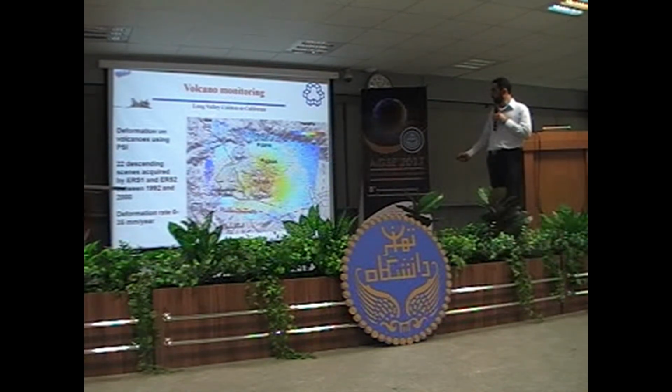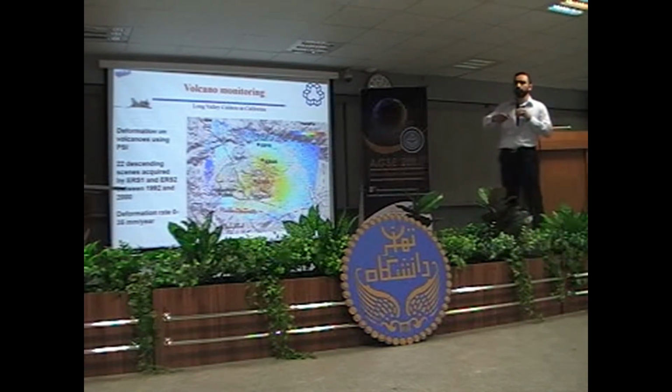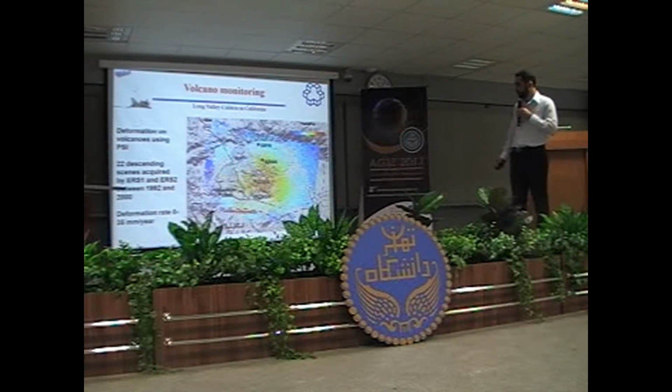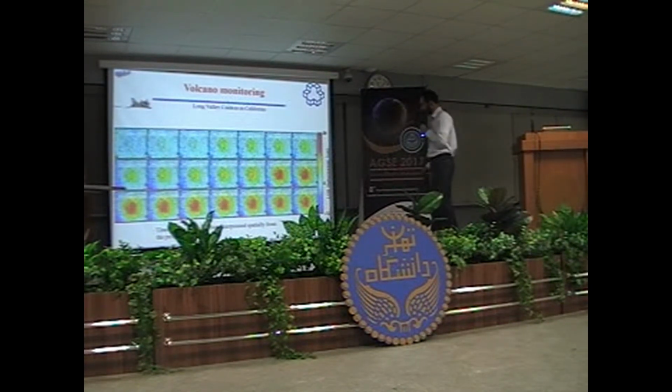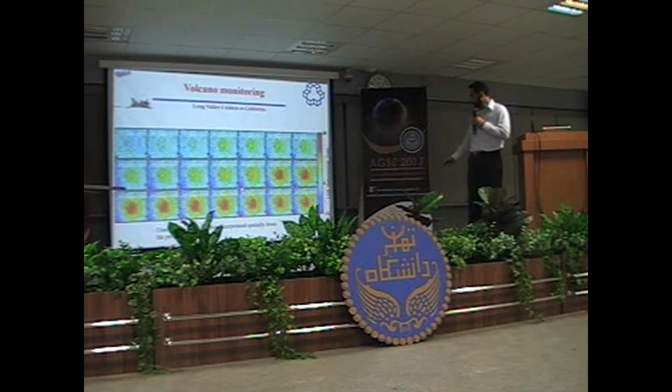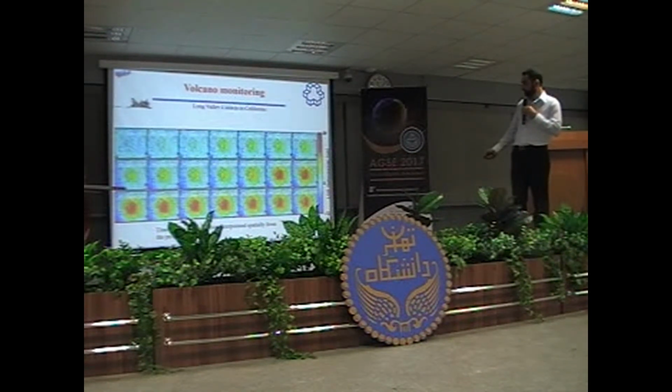Here, for volcano monitoring, you can use the different interferometric SAR images. If you look at this one, this is a volcano. Different interferograms can be seen at different times. And you see, when the volcano starts the eruption, there is uplift. The amount of deformation is quite clear. And by this time difference, you can exactly monitor how the displacement is occurring in the volcano. It actually needs a time series.